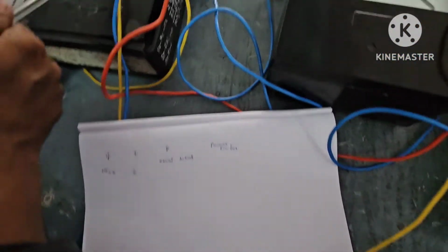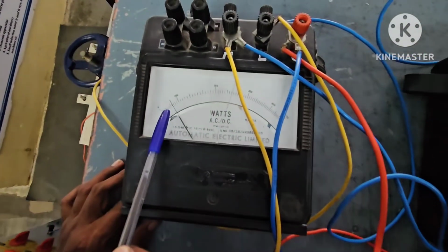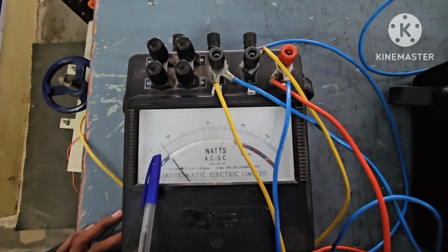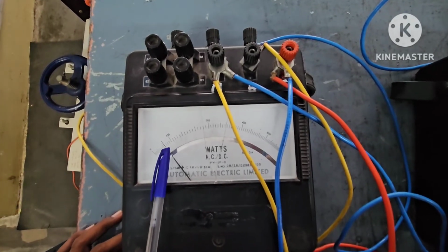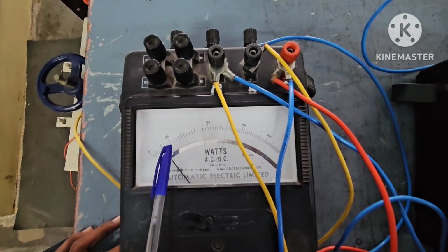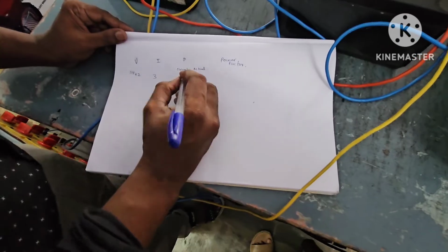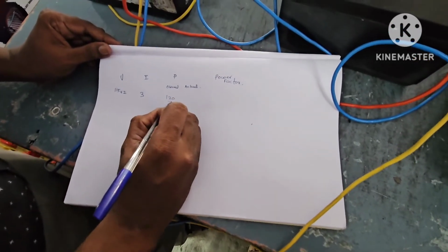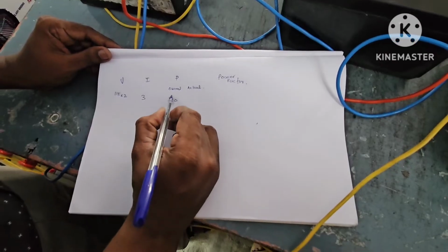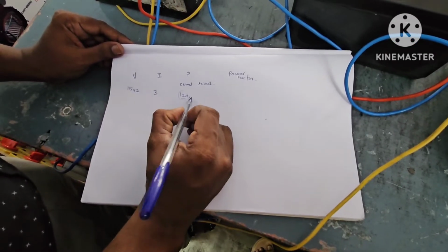Then I'll record the power. You can see power is about 100. Each division is actually 10. So 50, 100, 110, 120 watts. Around 120 watts power is being taken by the RLC load now. So let's record that power as 120 watts. Actually this power is the absorbed power, and we need to get the actual power by multiplying this by a multiplication factor,